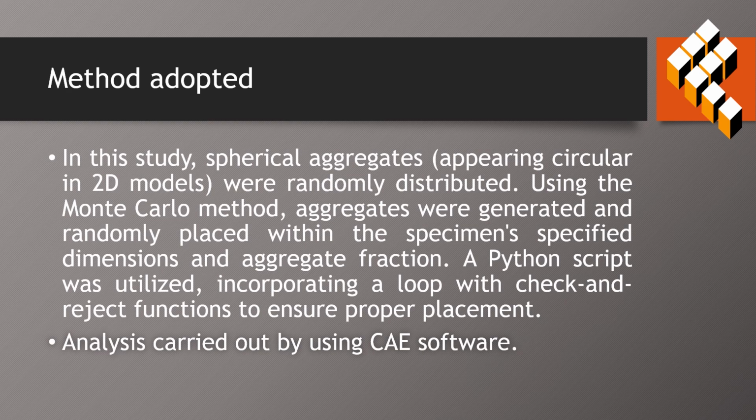Method adopted. In this study, spherical aggregates are randomly distributed using Monte Carlo method. Aggregates were randomly placed according to the gradation of the aggregate by using a Python script, and then analysis is carried out with the CAE software Abaqus.